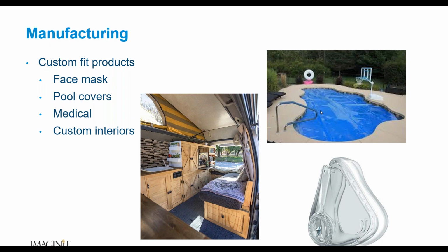It's similar with the pool covers. A company contacted me asking whether we could help with custom pool covers. Their vision was to set up a website where their clients could submit photos or video of their pool, and then the company could create a custom fit pool cover for them. RealityCapture will take video as well, so I can use video inputs, and obviously photos. I could go around and take a whole bunch of photos of my pool, or if I wanted to make it a little bit easier, I could take video.